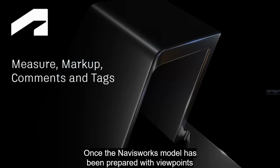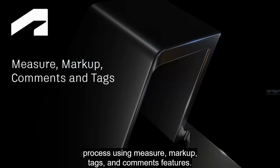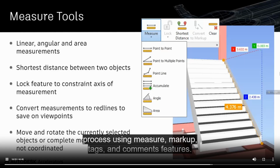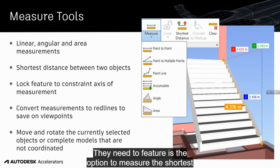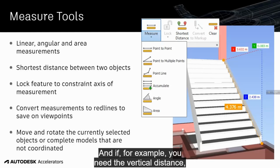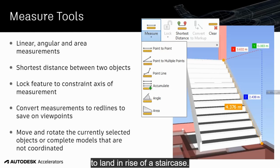Once the Navisworks model has been prepared with viewpoints and search sets, it is ready to support the model review process using measure, markup, tags, and comments features. The measure tools can be used for measuring distances, areas, and angles of the model geometry. A unique feature is the option to measure the shortest distance between two objects, and if, for example, you need the vertical distance, there is a lock feature to constrain the measurement to just the z-axis, as illustrated in the slide. That's measuring the floor to the landing rise of a staircase.